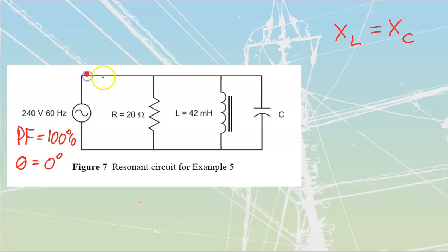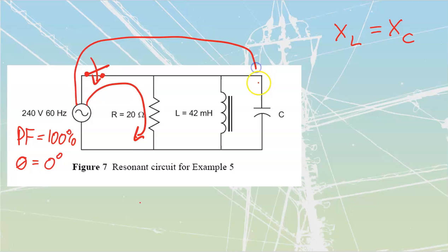So the instant that I close this circuit over here, again, I put a switch in there. When I close that switch, I'm going to get current that immediately starts, the 12 amps that's going to go through here. And then I'm going to get current that is also delivered out to this cap over here. And it's going to build up on that cap. It's going to drive electrons away from the other side like that.